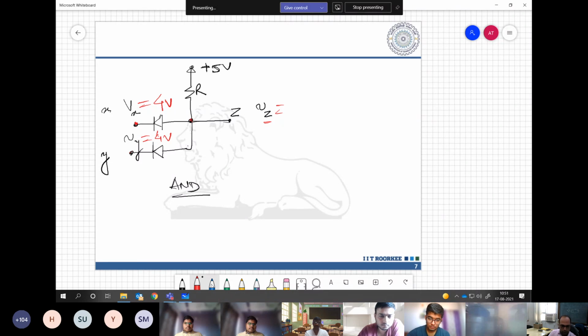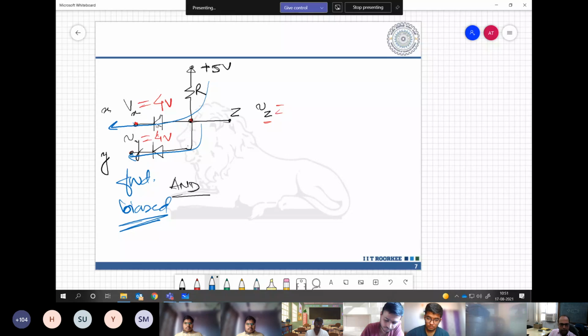Okay, first of all, first question. Which of the diodes will conduct? Both. Both will conduct, because of course the P side has more voltage compared to the N side. Okay, both will conduct, so both are forward biased. Now, when it is conducting, what is the drop across the diode? Ideally 0. No, practically, I am asking again. 0.6 or 0.7 volts.